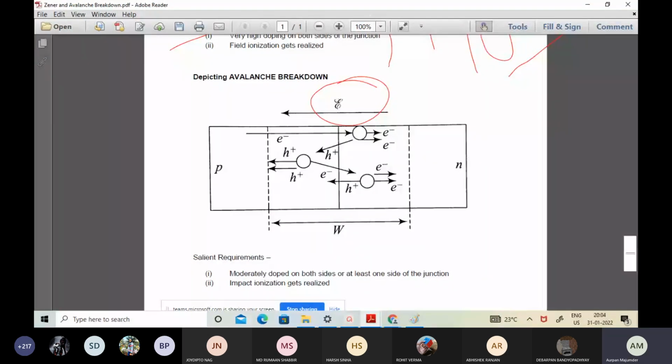And what you observe is something like this: the breakdown potential is in between say 5 to 8 volts, or around 6 volts or 6.5 volts, something like that. Though we quote it to be a Zener breakdown because Zener breakdown has its primary effect over there, in essence, that is also part of device physics, it is having a combination of the two.